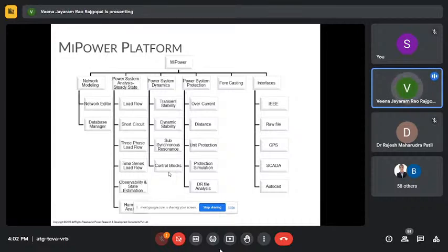So you have general philosophies for how the distance relays have to be set. I'm just telling an example. What should be the percentage, your philosophies, all those things can be modeled. So overcurrent and distance are the graded protection where the system parameters are going to play a role, and the others are the unit protections. Most of the unit protections, whatever is there in the field, can be modeled in MyPower.